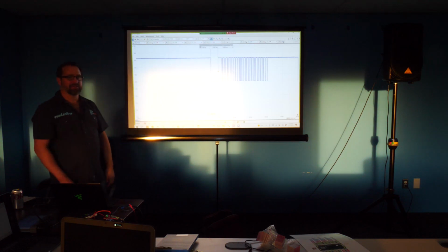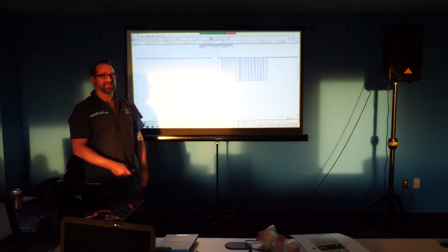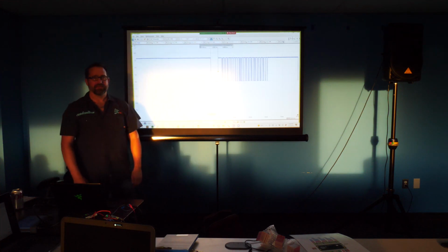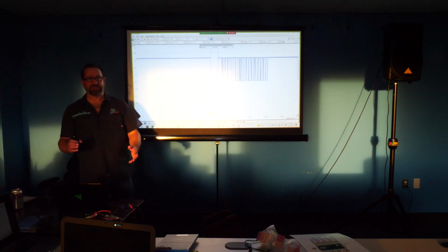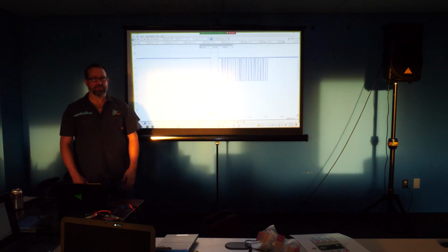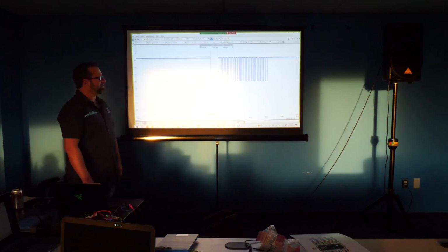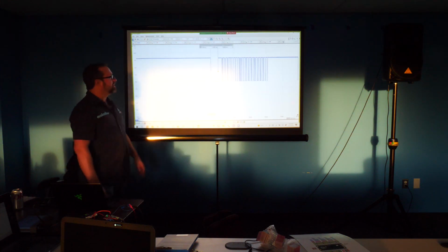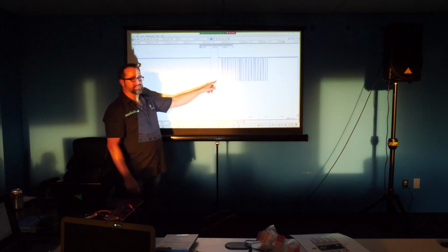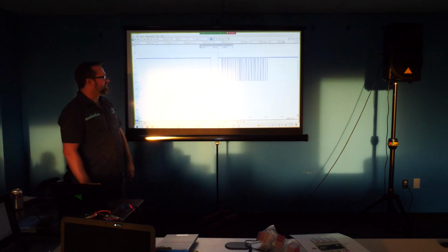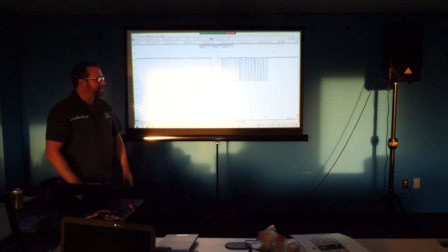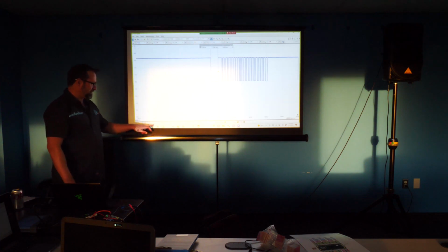Yeah, that's something you'll run into a lot in embedded systems. 1 or 0 don't necessarily mean on or off. It's about what the active state is. In this scenario with this sensor, the active state is low, so it's inverted.